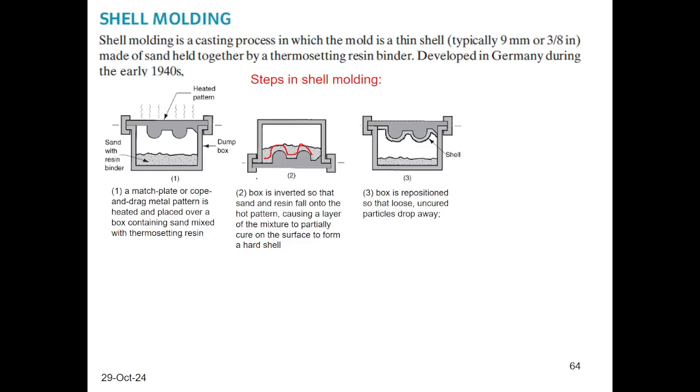Then we once more invert the box, and the cured sand particles just stay wrapped to the pattern, and the layer will be in the shape of the casting.